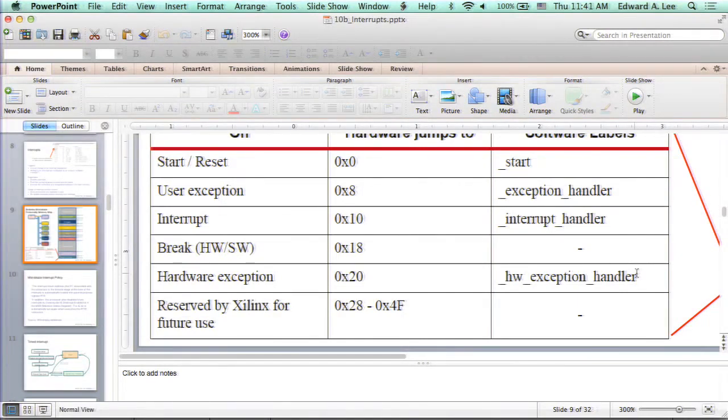At address 0 is, in this case, just an address, not a jump instruction. So now, great, we actually have 32 bits. You can put the interrupt service routine wherever you want now. So the hardware just says, the only way I'm going to use that location is to get that address and branch to that location. This architecture has a user exception, which is an exception that you can trigger in your code that will jump to a location that you specify by loading it into that memory location. It has a single interrupt request, and you specify the address and stick the address in this location, and so forth. Okay? So that's the processor that you will deal with in the lab.